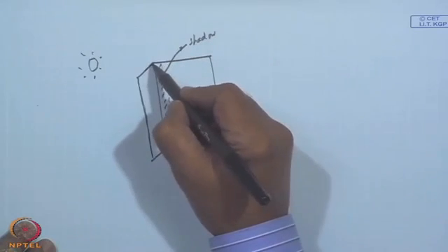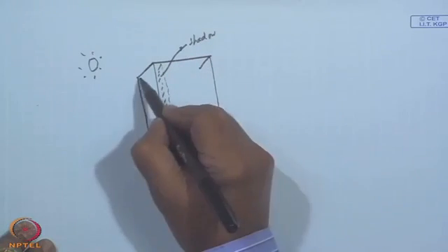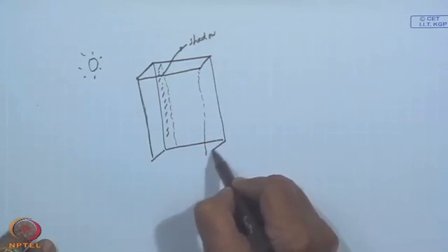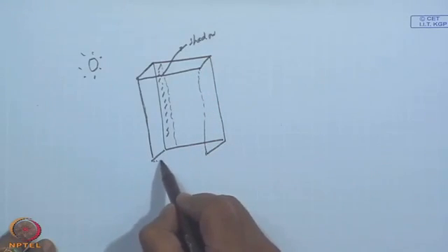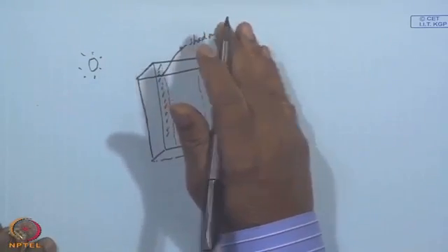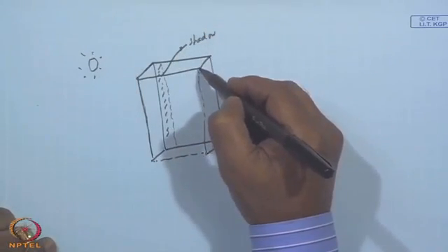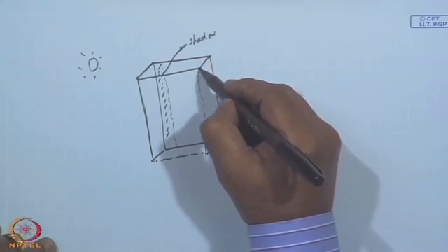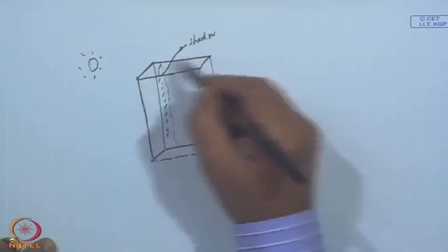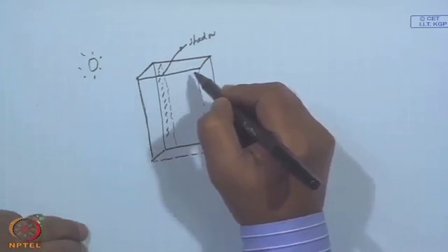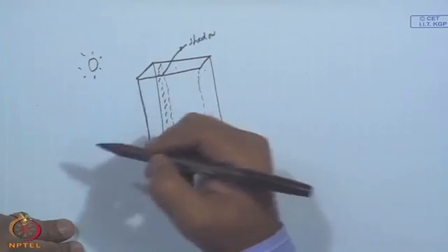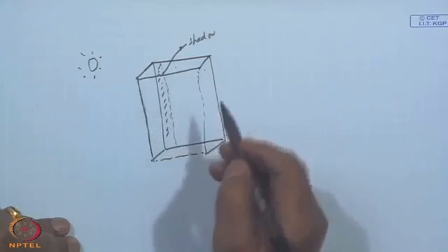So, if you have an overhang and two wing walls, and bottom is not necessary, but usually that makes it a box type window, there will be pretty good coverage. And I have not yet exactly made the calculations, but I suspect that if you have got wing walls associated with the overhang, you may treat the overhang as if it is infinitely long, because it is either shaded by this or this. So, that is a different issue.